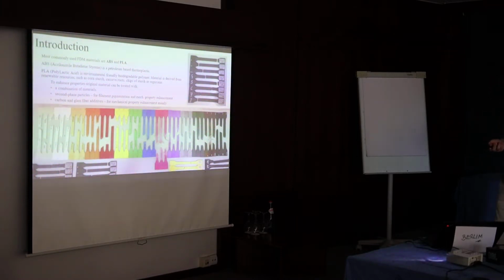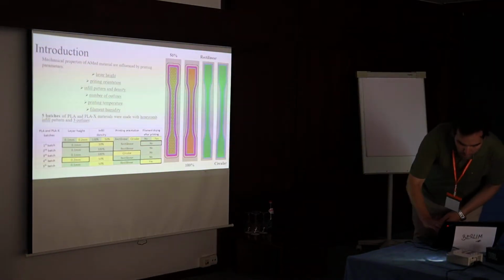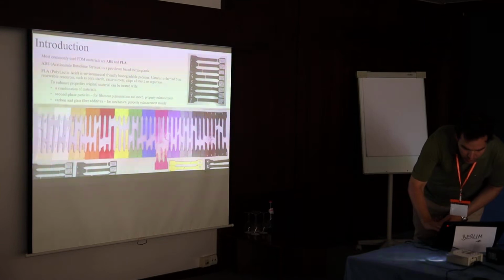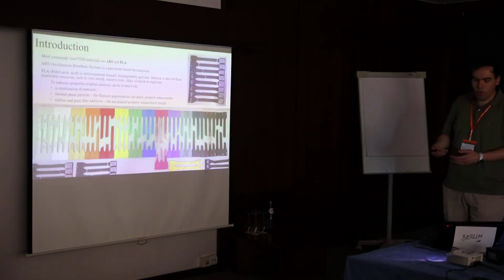One obvious example is that sometimes PLA material is shipped in different colors. They use different pigments, which are like second phase particle additions, and they not only change the color of the material but even the nature of fracture. Some specimens with some colors fractured in a brittle fashion, and some fractured with ductile type fracture. But all in all, they ship this as the same material, even though now it's not.